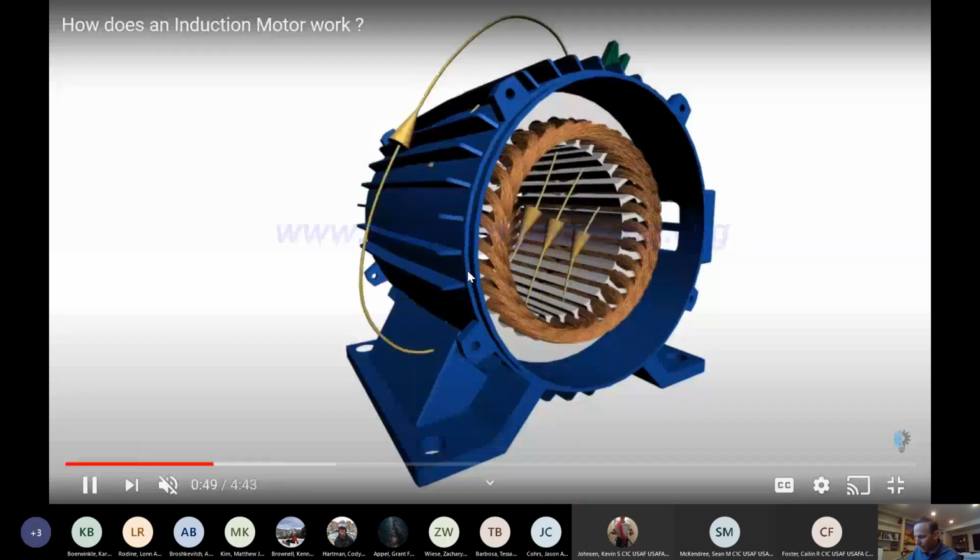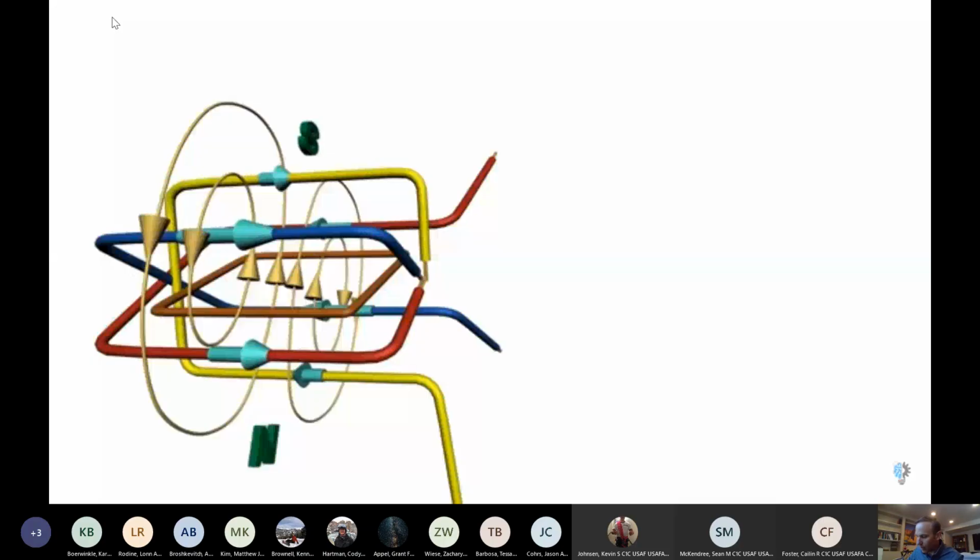They're all going up and down differently. So at any given point in time, even though these outer windings do not move, they're stationary, because it's alternating current, it creates the effect of a moving magnetic field. You can see that the blue lines indicate how the current is changing in the wires, and the yellow lines indicate how it's moving, creating a rotating magnetic field.